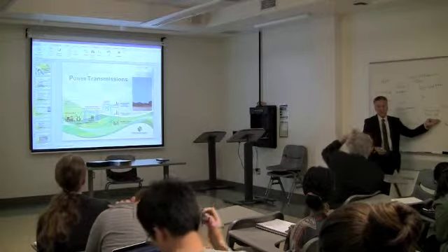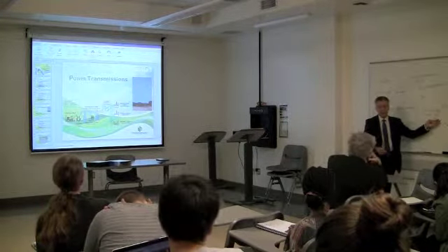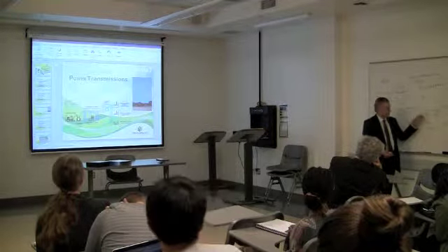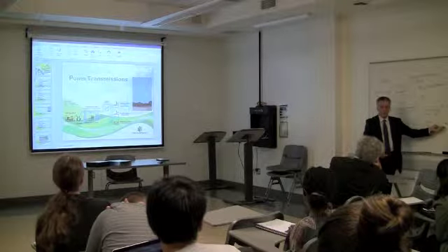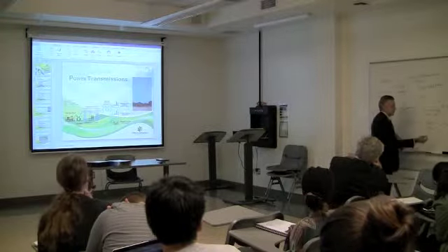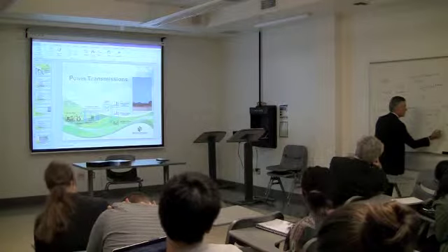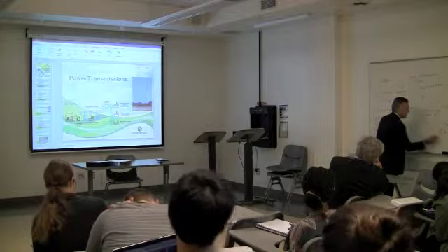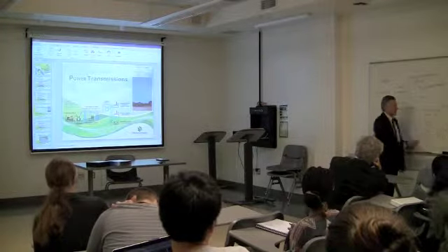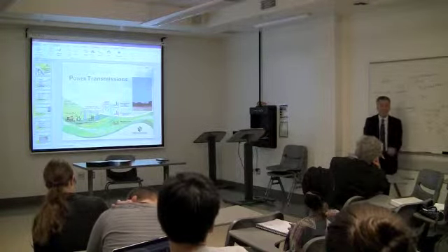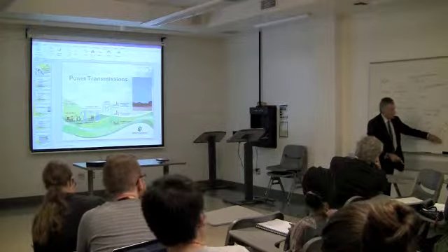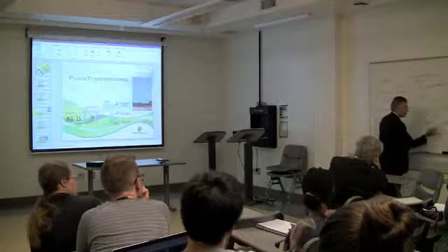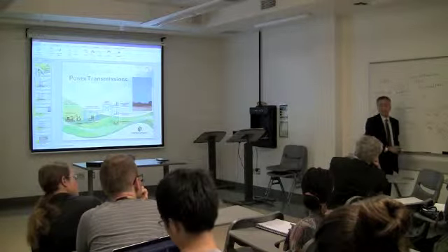Then we bring it to the distribution station or receiving station that has the ability to handle that. In that station, we have 20, 30 transformers to step it down to basically 66 kV, 38 kV, and 12 kV. That goes through the distribution system. When it comes to this campus, it comes in at 66 kV.